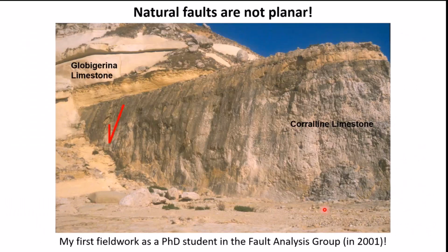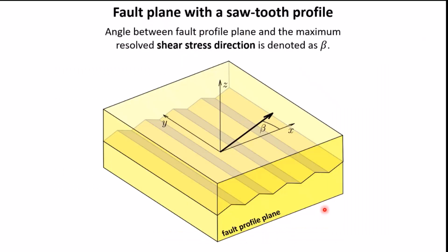Okay, so I could ask you, what's the friction angle of that fault? And it will obviously depend also on the orientation of the maximum resolved shear stress, because Patton only solved the problem in 2 dimensions. Right. So I thought, I couldn't find anyone. Please tell me if I'm wrong, but I don't think anyone has solved this problem in 3 dimensions before. So I went along and said, okay, I'm going to solve Patton's problem in 3D.